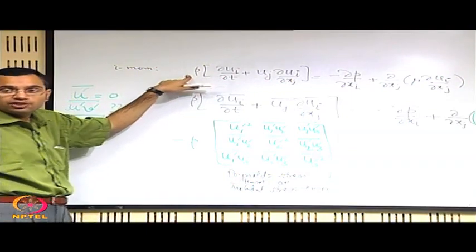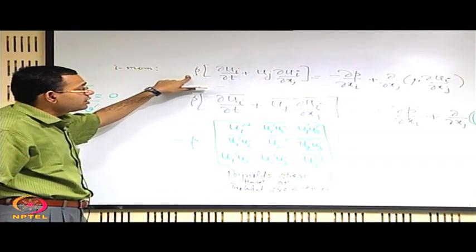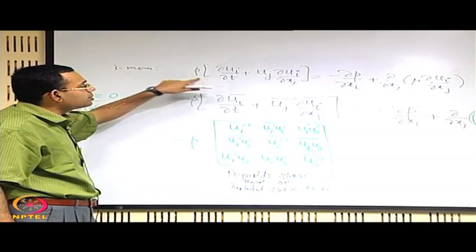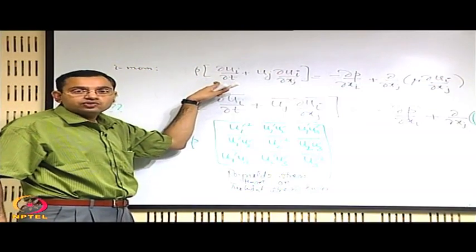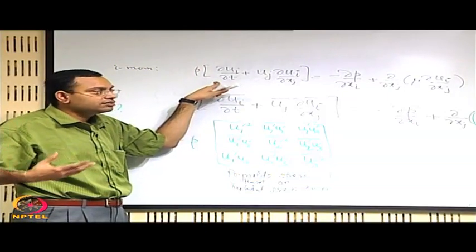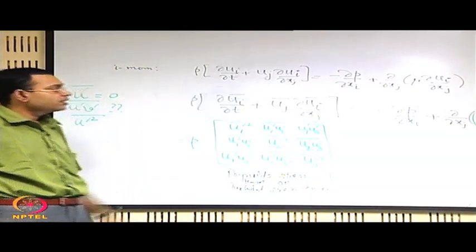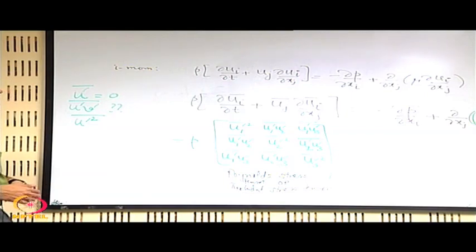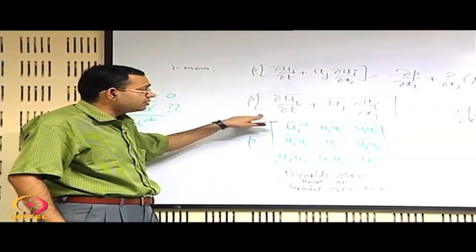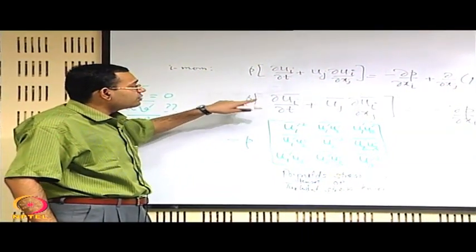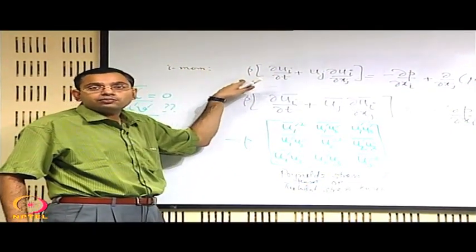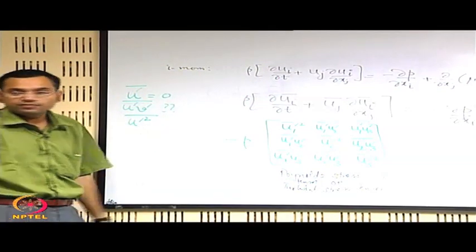like Newtonian fluid and Stokesian fluid are satisfied. But it is not so easy to deterministically obtain the variables from the original form of the Navier Stokes equation because of the uncertainties in maybe boundary conditions or initial conditions. So, what we concluded is that their statistically average forms are so-called deterministic, and therefore we statistically average them. One good thing of the non-averaged form was that the system of equations was closed. So, the number of equations and the number of unknowns were matching with each other.